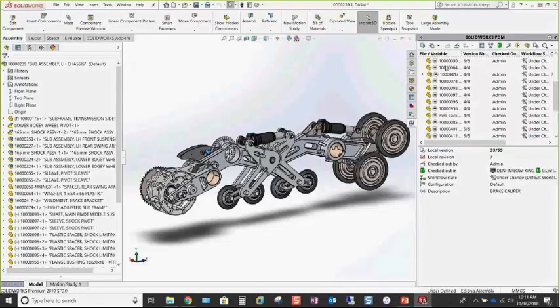On a file that's checked in, I have the ability to change state, so from state to state through a transition. The transitions that are available to me, if it's checked in, I can run from right there. Additionally, one thing that I'd like to show off here is the where used. So right from inside of SolidWorks, we can run a where used report.